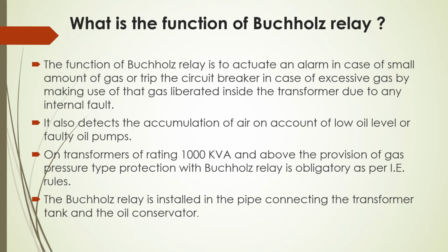What is the function of Buchholz relay? The function of Buchholz relay is to actuate an alarm in case of small amount of gas or trip the circuit breaker in case of excessive gas by making use of that gas liberated inside the transformer due to any internal fault. It also detects the accumulation of air on account of low oil level or faulty oil pumps.